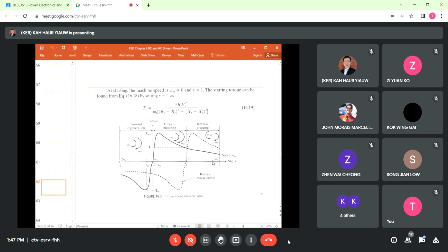The developed torque, which is in the same direction as the field, opposes the motion and acts as braking torque. Because S is greater than 1, the motor currents are high, but the developed torque is low. The energy due to a plugging brake must be dissipated within the motor, and this may cause excessive heating of the motor. This type of braking is not normally recommended.